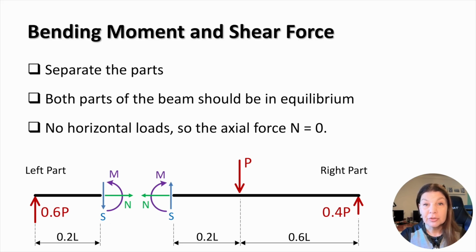The internal forces can be found from equilibrium equations written for only one part of the beam. As a result, it's convenient to select a part which has easier geometry and a smaller number of forces. But what we need to remember is that these are internal forces and moments, and when we bring the beam back together, they should always cancel each other out.